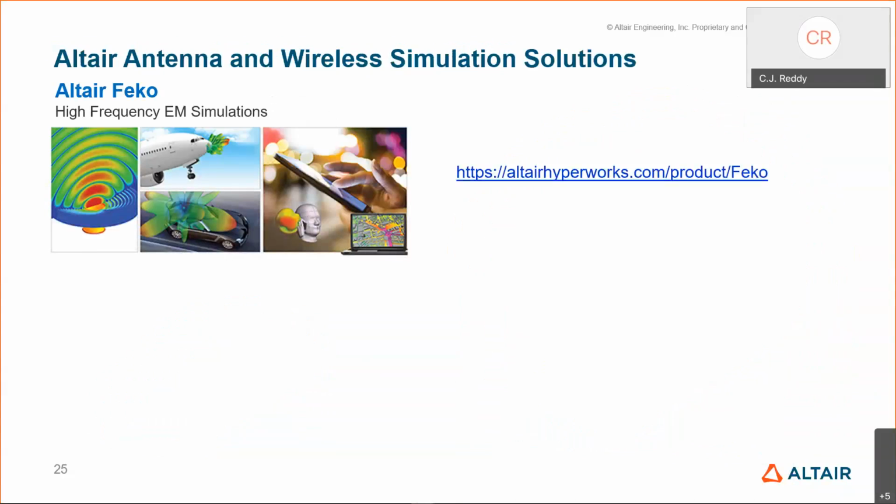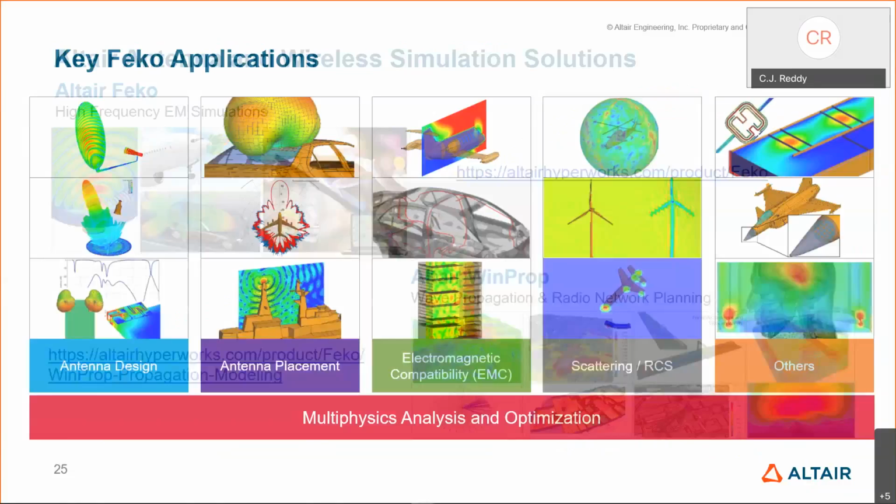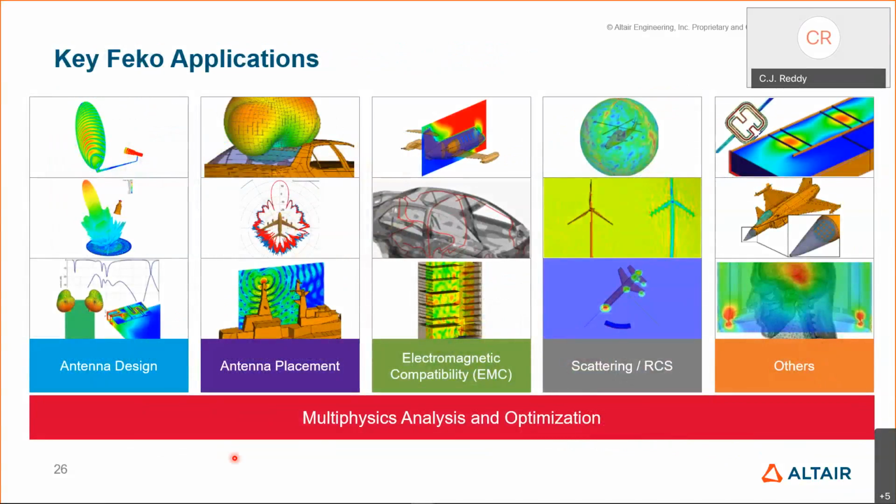With that, we offer, of course, from the Altair side, Altair Feko as one solution for such problems to solve Maxwell's equations numerically, but also WinProp that I already talked about before. Of course, with respect to applications, with these tools, one can solve antenna design, antenna placement, electromagnetic compatibility, scattering and RCS, and other applications as well.